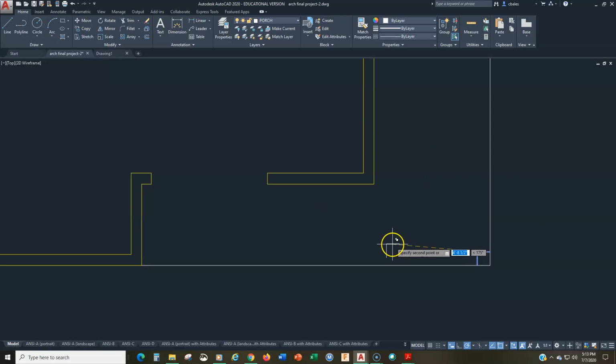And I'm going to move the handle so that it is right there. But that's not correct. If I click, that would place the post there, and clearly the post is on the wrong side of the edge of the porch. So what I'm going to do now, I haven't clicked yet, I'm going to track up right there. And you see how that creates that green dotted line intersection? I'm going to click, and then there we go.